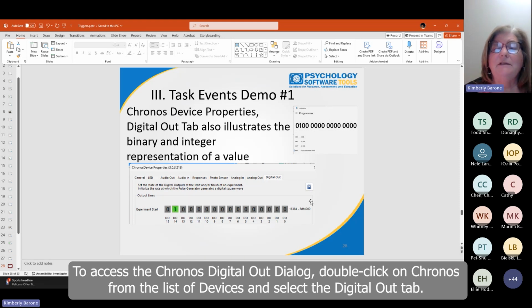And hopefully you can see that this works very similar to this programmer calculator. Again, Kronos labels its digital outputs 0 base. So again, this is digital output 0. This is digital output 15. This is interactive. You can click here. So I clicked on digital output 14 to show that that should be set to a 1. And over here, that shows the same integer value that we saw with the programmer calculator. So this can be super handy just because you're already working within E-Studio.